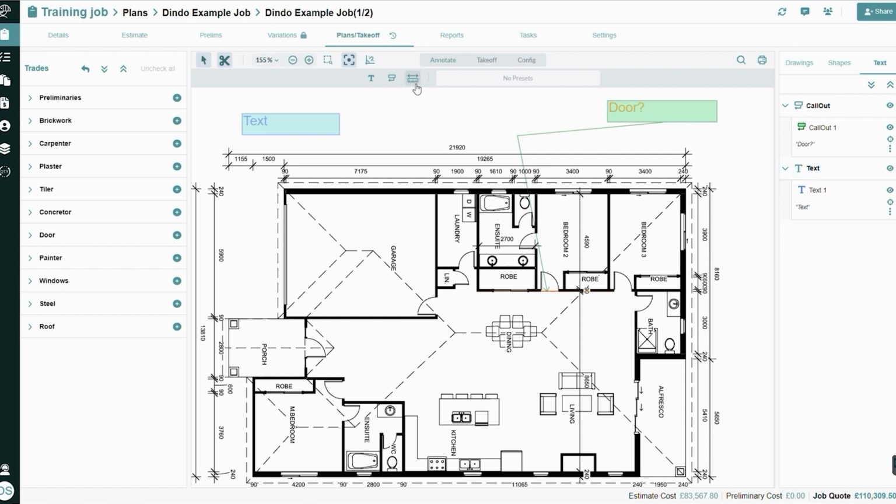Config we looked at. This is just a ruler. So if you want to check the length of something, but you don't want to do takeoff, you can just use that little ruler. And I know from here to here is 17.088. Grand. I'm not going to do takeoff, but I just wanted to know what that length was, because I wanted to double check something. Maybe that would be a good thing when you do your scale, and then you want to double check what that is.